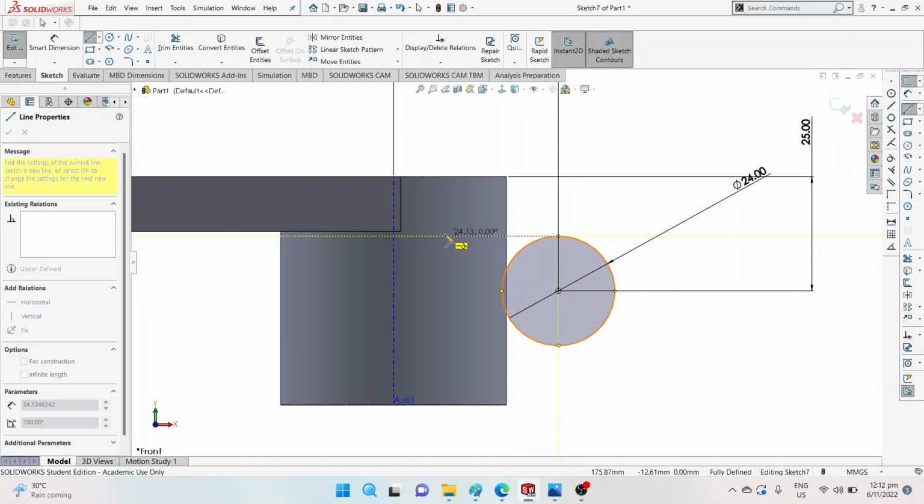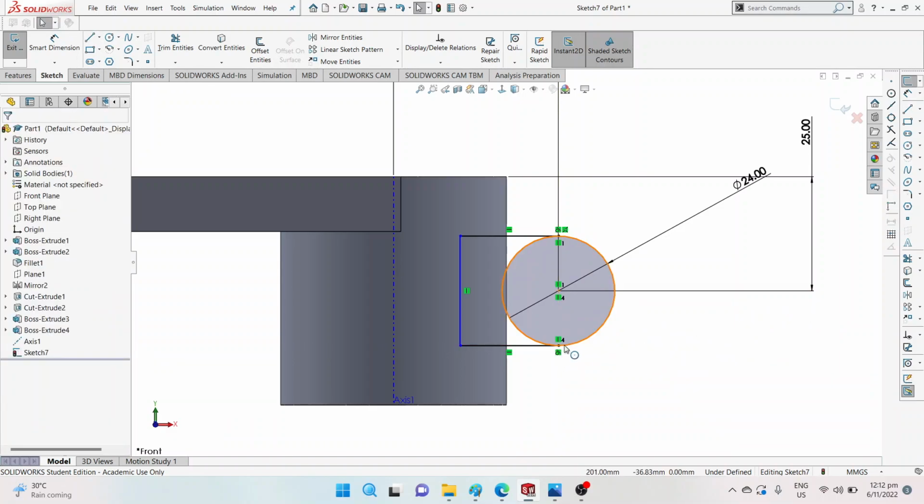Because this is a straight line, I'll go in and come down. I make use of the tracking so that I need not enter my dimensions, and I know that it is perpendicular and also tangent to the circle. Because it's a straight line, it will end at the circle at the 180 degree, or the 6 o'clock mark and the 12 o'clock mark.